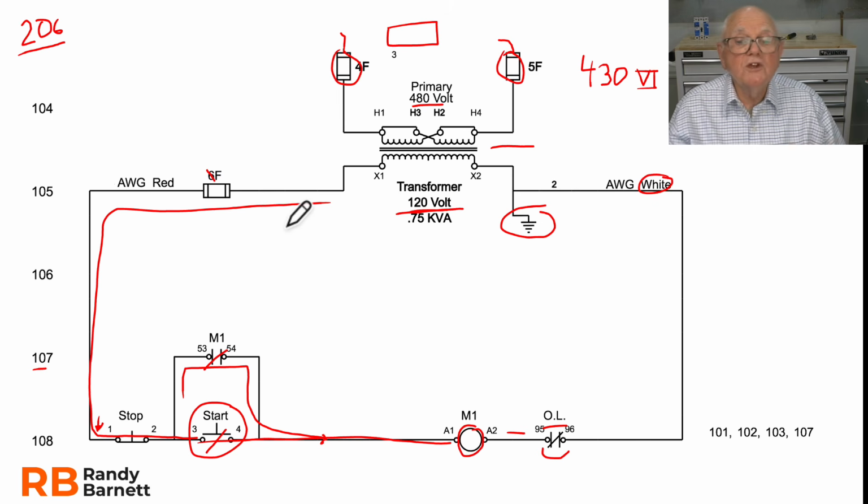Oh, so all of those other rules back in Chapter 3 still apply. What about my raceways and all of that I'm going to put this in? Yeah, that's all found in Chapter 3. So that information still applies from Chapter 3, except for the sizing of these conductors, we can do something different.